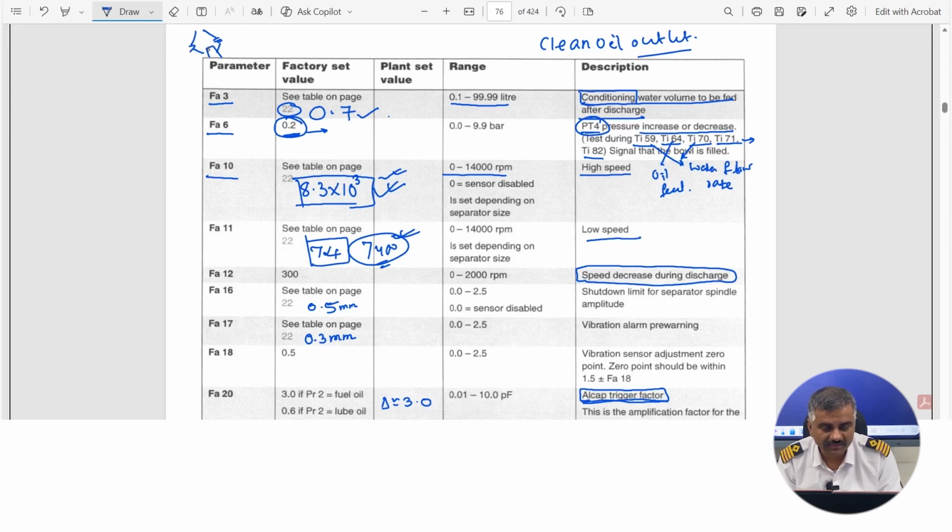The vertical shaft assembly, which was taking up the bowl load, suddenly experiences a lesser load, so the motor is continuously rotating, trying to rotate the bowl at the same rpm, but since there is a load reduction, there will be a speed reduction in the shaft.